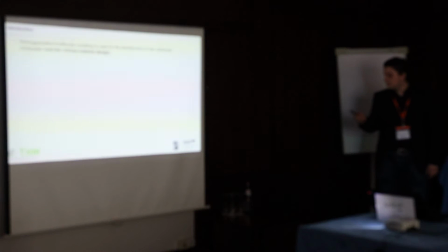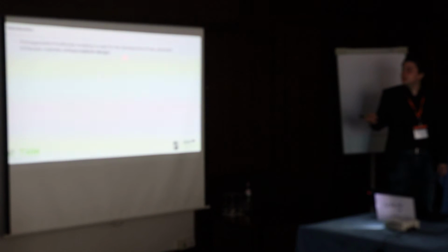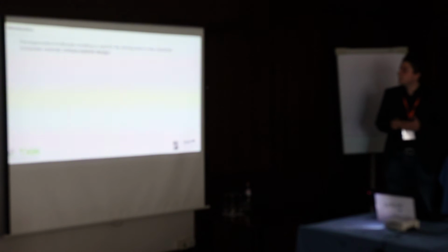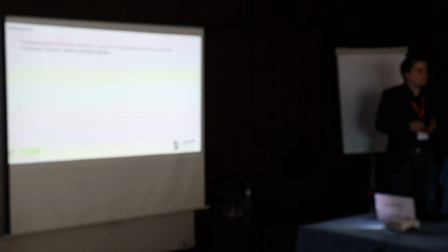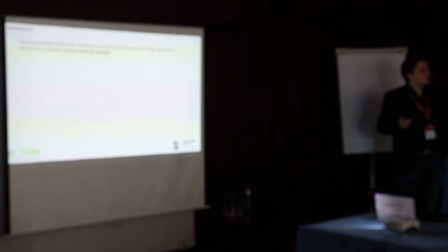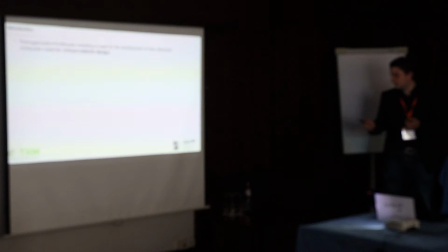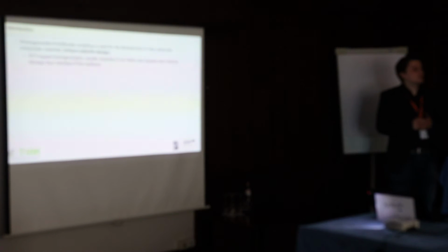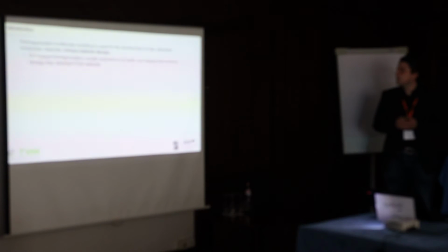So first of all, homogenization, multi-scale modeling, is very interesting for the development of new and advanced composite materials. The idea is to design a material virtually in the future. So what you need is information on the microstructure, information on the mechanical behavior of the constituent, and you want to obtain a macroscopic response or at least an estimation of the macroscopic properties. And in this case, for the numerical part, the FFT-based homogenization is expected to be faster and require less memory than the standard FEM methods.